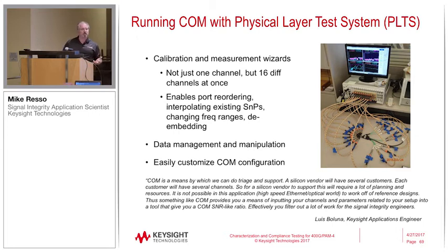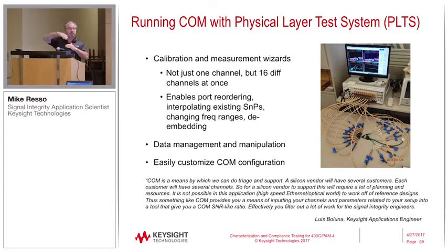It's not necessary or required, but this may be something you want to do. We know that crosstalk varies as 1 over the distance squared between the victim and aggressor. So as you move away from the victim, the crosstalk is going to have less effect from an aggressor that's further away, but you can still choose to do that if you'd like.